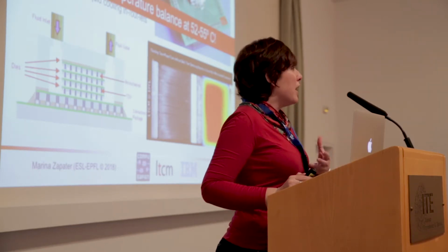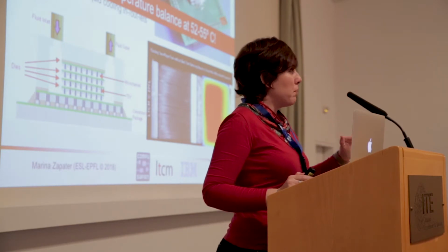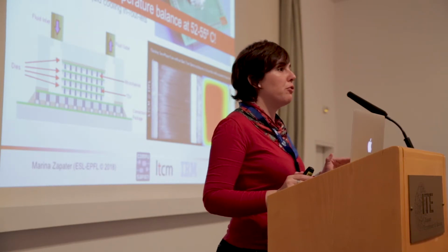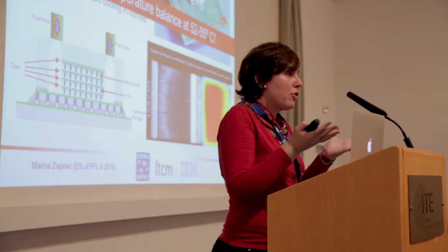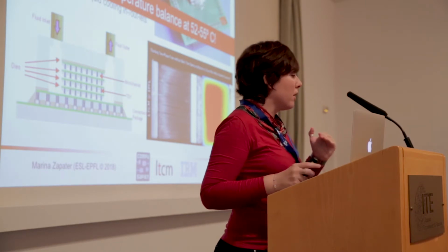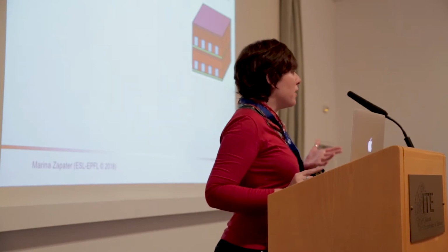And the thing is that liquid cooling has very nice properties, right? Because as it's liquid, it helps us balance the temperature across our chip, which is always beneficial, right? If you're able to balance the temperature in your chip, you can potentially bring the temperature slowly up, or at least stress the whole system, rather than creating a hotspot that is going to limit the performance of everything. So up to that moment, okay, we can build a 3D chip, but as I was saying, we need to have ways of simulating this. And that's where 3D-ICE came in.